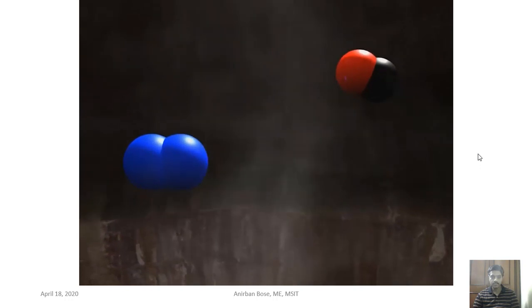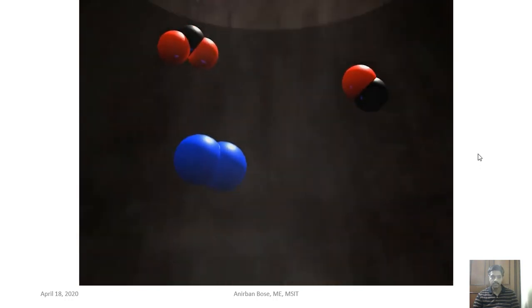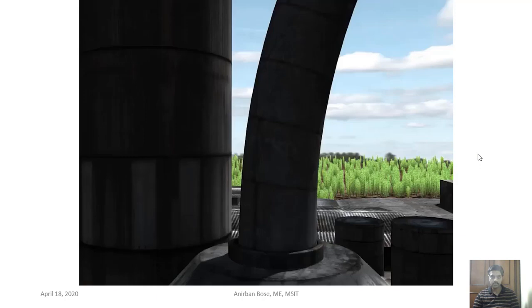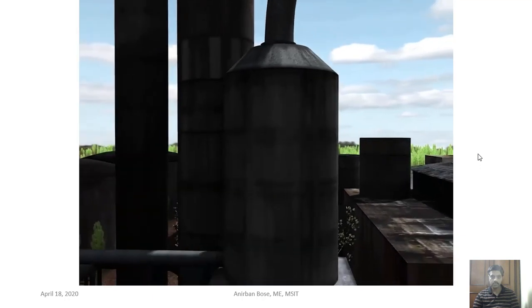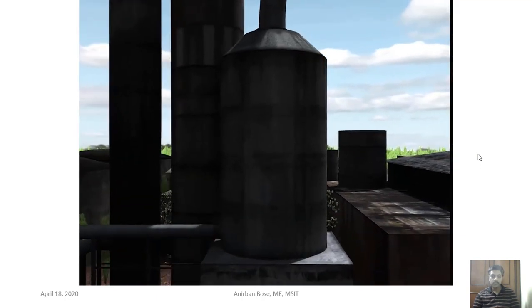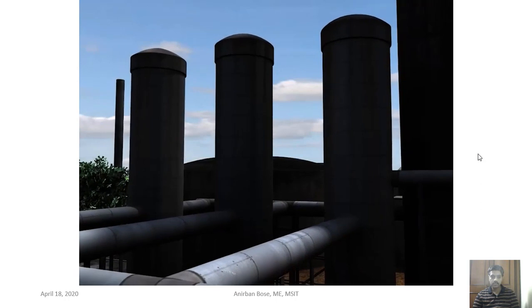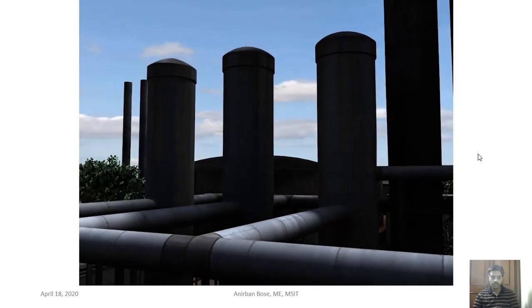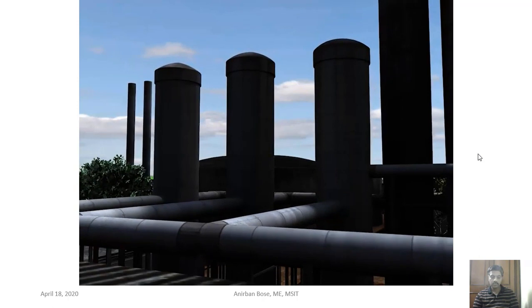The unused carbon monoxide, along with nitrogen from the hot air and carbon dioxide, passes through the outlet at the top and enters the dust catcher, which removes dust and other particulates. The dust-free gaseous mixture is burnt in special burners, and the heat produced is used to heat the air that is blown into the furnace.